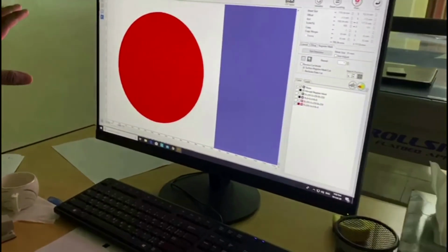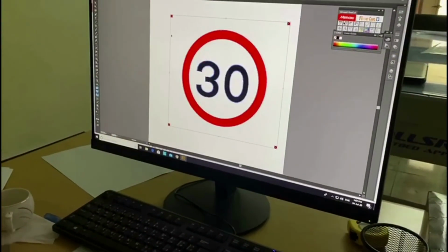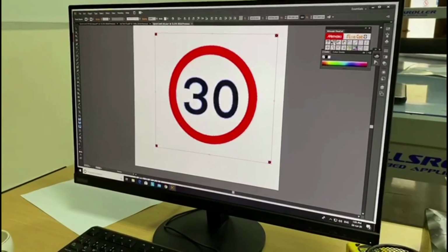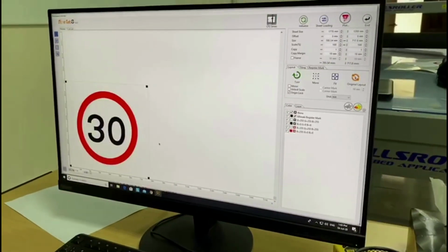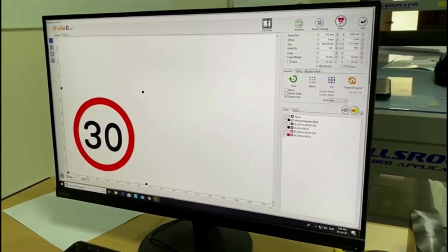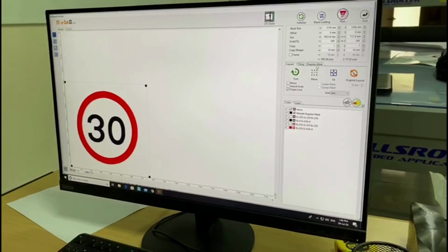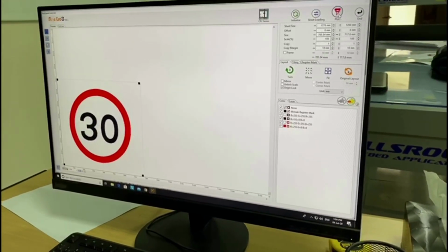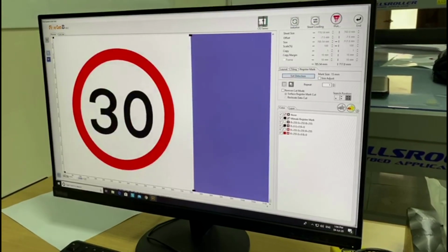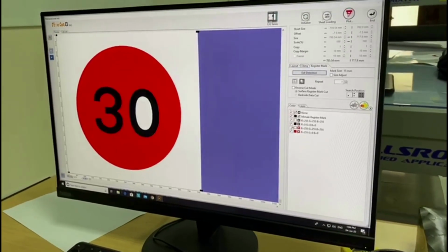Cutting. Machine, CF2 Series, 1218. First of all, the cutting machine should be prepared before sending the job order from the software. A cutting test must be done first to assure that the blade will cut the required depth of the 3M sticker. After that, the conditions of the machine, cutting pressure, speed, acceleration, offset, origin, should be set depends on the required work.